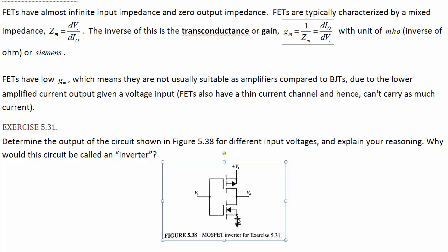Well, because this has a very high resistance, this voltage is going to be raised somewhat compared to this one. Imagine if this resistance was very high as well, then this would be in between. And so the gate of this one relative to its source is going to be negative. So that's when this P-channel MOSFET is turned on. That means this has a very low resistance, and so Vout is just Vs. It gets pulled up to this top Vs. So if Vi is 0, Vout is Vs.